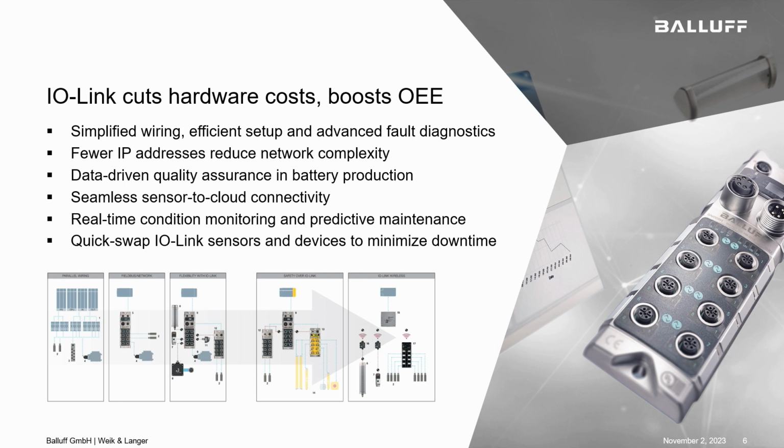At the end we can reduce the number of fieldbus modules, because we can work with the IO-Link I/O modules to collect all these sensor data instead of using fieldbus modules. And then we don't need to always have an additional power supply on the module or a fieldbus cable on the module. It's all on the 3-wire sensor cable. This reduces the cost as well.